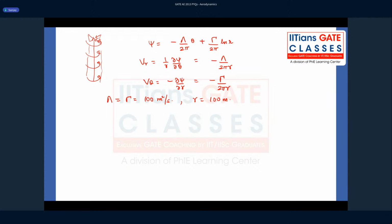So what is the velocity at a point, guys? Velocity at the point is going to be the resultant of these components of velocity, which is square root of Vr square plus V theta square. So if you just substitute, it's going to be 100 by 2 pi 100 square plus again 100 by 2 pi 100 square.